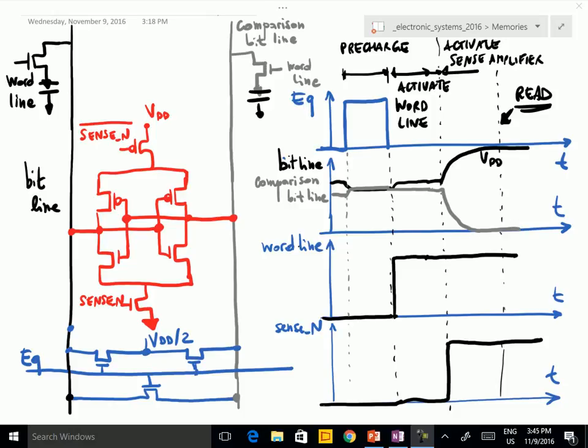One thing that is important to keep in mind is that there's a basic difference between the DRAM and the SRAM architecture, as you already know, but it's worth repeating. Of course, in the case of DRAM, the information is stored in the charge on the capacitor of each memory cell. And of course, these capacitors in practice are leaky, in the sense that this charge gets lost. So the capacitors get discharged in time, and therefore naturally lose some information.